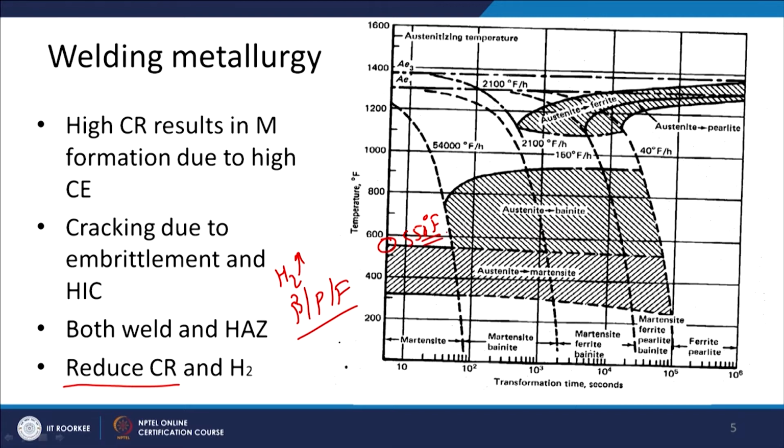So, if we give any preheating to the steel, the formation of the martensite during the welding is avoided. Normally 600 degree Fahrenheit preheat is preferred, but working with the higher degree of preheat is difficult primarily due to working with the hot plates as well as the oxidation tendency of the steel.